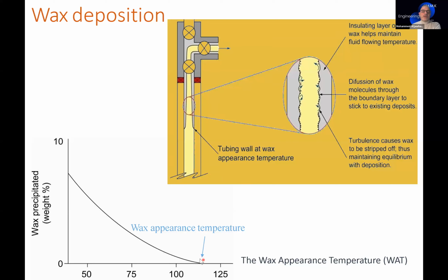When we study the PVT and reservoir parameters, we will know exactly when the wax appearance temperature could start. So how can we increase the temperature, how can we take action before seeing wax, or just at the start, before this problem increases and plugs all the fluid flow from the reservoir to the surface? So how can we remove this wax and get rid of this problem?